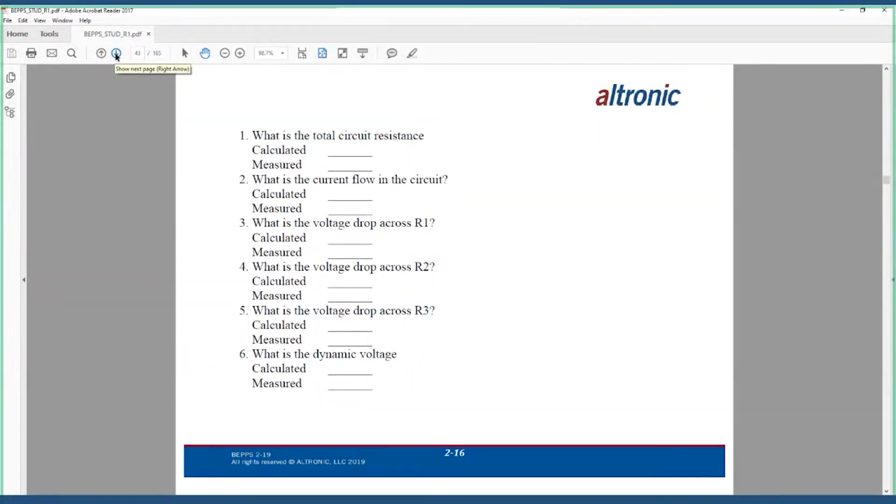And I did one of the best examples last week, where we use Ohm's law on a regular basis to calculate what we're doing with some of the circuits where we're taking a milliamperage signal, but we're converting it to voltage so a computer system can read it. There's not a computer system in the world out there, a car ECM, an Allen Bradley PLC, an Altronic product is no different, where we truly measure amperage from, say, a pressure transducer.